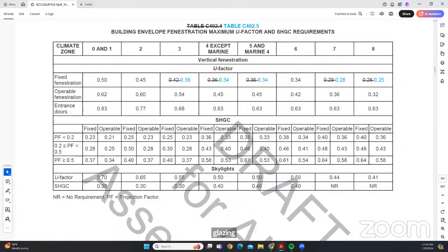Now, remember, commercial glazing and residential glazing fall under two categories. For residential, it's very plausible to have a really aggressive U factor because they're mass produced and they're able to do it. A lot of the commercial items are one-offs. They have some, but they're not mass produced, so they can't get those U factors that you may be able to get on the residential side.